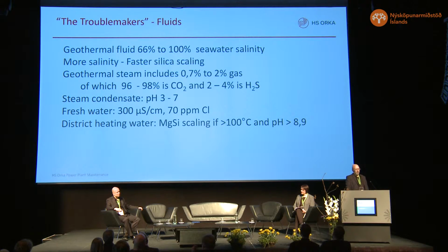Our fresh water, because we are producing district heating water from fresh water, has 300 microsiemens per centimeter conductivity and 70 ppm chloride. It is actually very low, far below all drinking water standards, but the chlorine content is 10 times that of the Reykjavik system. So it can be tricky when heated or when we have some leaks somewhere.